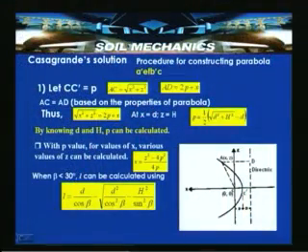So, Casagrande's solution, if you look into the procedure for constructing the parabola, A dash E F B B dash C, that is a portion of the parabola is shown here. C is the focus and D is the directrix, and CC dash is the distance P. Let CC dash be equal to P, then A is a point on the parabola with the coordinates x and z, and C, the focus, has coordinates 0, 0, and AD is this horizontal distance.